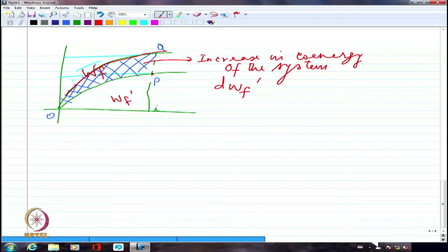At steady state, the current should not change is your perception. That is not steady state. If the initial value at the beginning of a cycle and the final value at the end of the cycle are the same, you call that steady state. Steady state does not mean it is a constant. You may say, no, you have simple harmonic oscillations, don't you say it is steady state? It is oscillation, of course it is oscillation, but it is steady state.